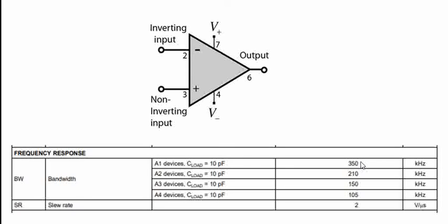That's what it meant. So while there might be a little confusion, especially for the beginners, about what this bandwidth meant, if you take an analog application, you have a signal that varies at the input. So analog itself is varying, right? And that variation could be slow, could be faster. There could be many different scenarios. So the higher the variation, it means the higher the frequency at the input of the op-amp, right? Indirectly, you are saying the signal is switching faster there. The variation of the input is faster.